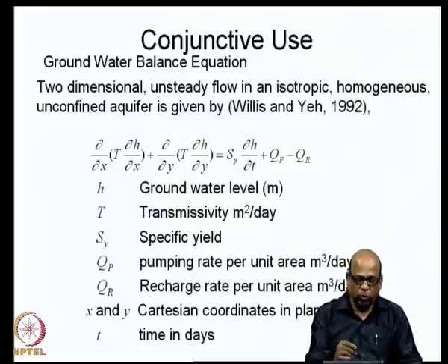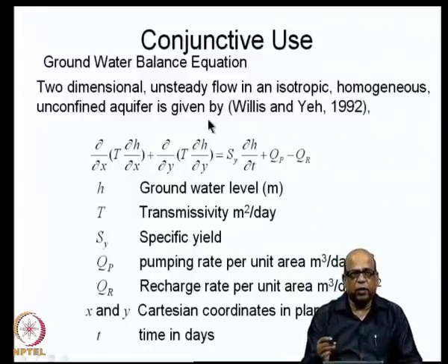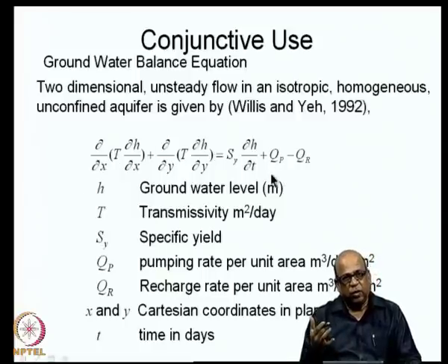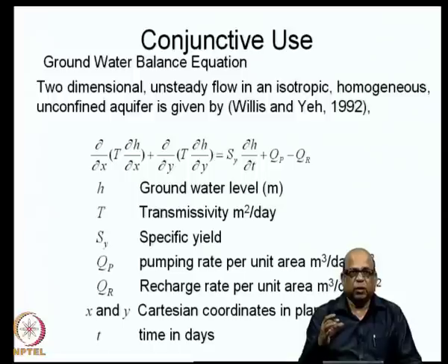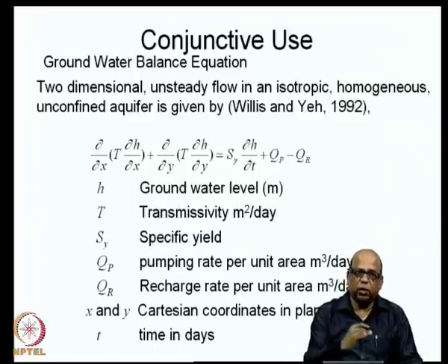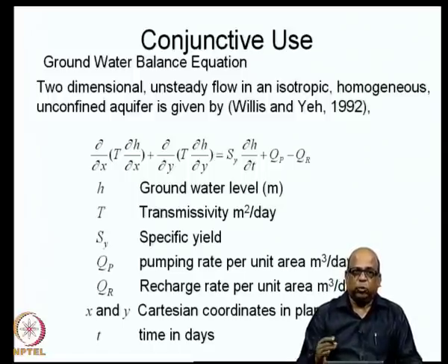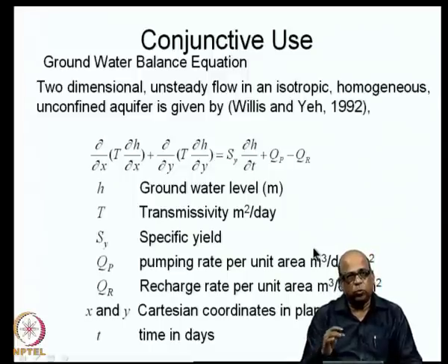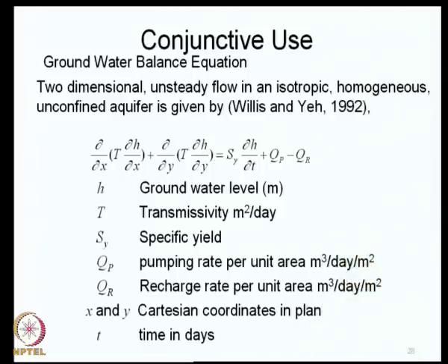However, you can go into a two-dimensional unsteady flow model and write a finite element code for this, convert this differential equation into a finite element numerical method, and then at each element you write the continuity equation. So, these types of complex models are available in literature, you can just go through it, but the broad philosophy of the systems model remains